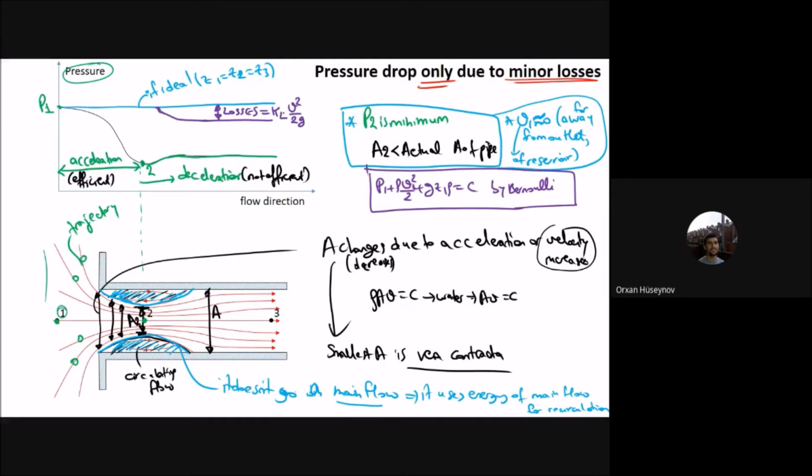Okay, so if you are looking for the loss coefficient in pressure terms, you should multiply it with this quantity, rho g. If you multiply with rho g, you will get the pressure terms, with the unit as pressure. So we can put it here, or it will be KL rho V squared by 2. They are the same stuff. This one is in meters and this one is in pascals.